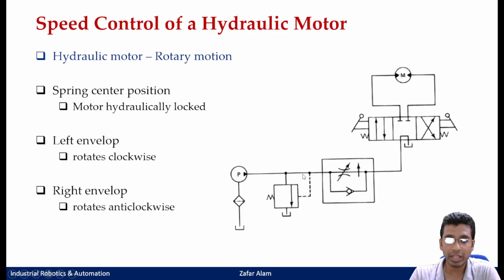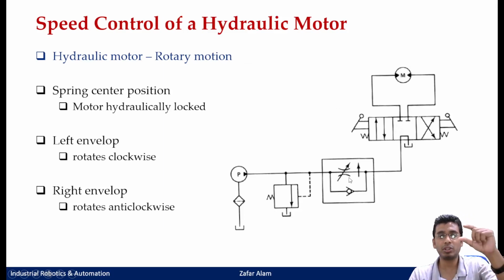During any motion here, for example, the fluid cannot flow through this path. It is forced to flow through this orifice, and if you restrict the orifice to, suppose, 20% of the opening, then of course your motor would rotate at 20% of its speed. If you restrict it to 30% of the opening, it would rotate at 30% of the speed. Okay, right? However, when the liquid is coming back from the other side, which is not the case here in case of a motor,